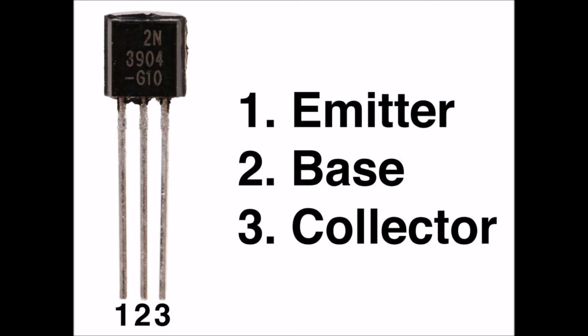It is expressed as HFB, static forward current transfer ratio, or HFB, small signal forward current transfer ratio. The smaller the base current, the closer the collector current comes to equal with the emitter current, and the closer alpha comes to equal 1. Typical value of alpha for junction transistor is between 0.92 and 0.98.